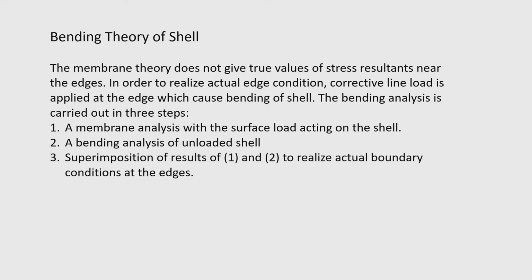Then we will do the bending analysis of the unloaded shell, because when we consider the bending moment in the shell, the order of the differential equation increases. Therefore, the characteristic equation will have a high order; it can go up to an 8th order equation. So if we use the unloaded shell analysis, then we will find an equation of a wave which will get damped out very quickly.